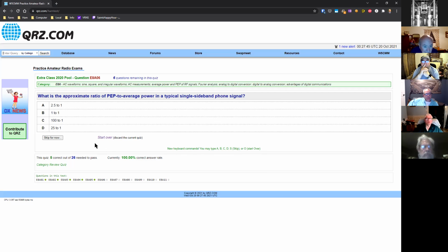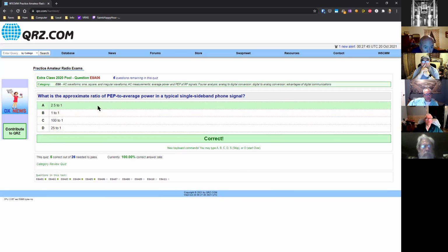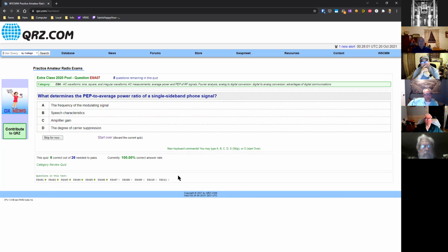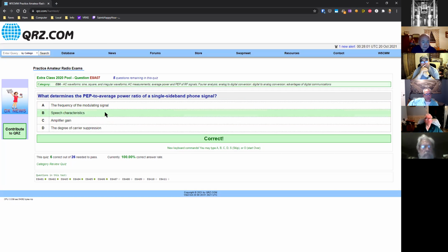Like alpha? Yeah, 2.5 to 1. What determines the PEP to average power ratio of a single sideband phone signal? Bravo. Yeah, Bravo, speech characteristics.